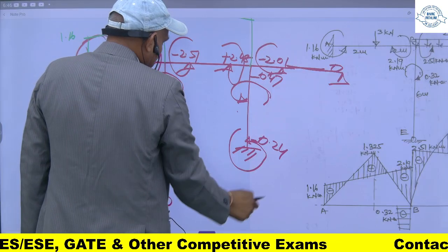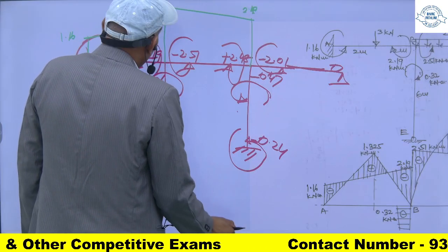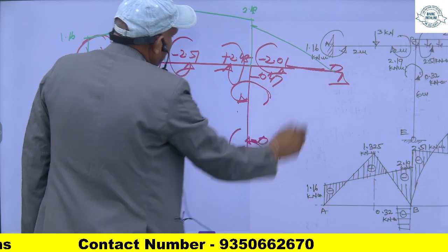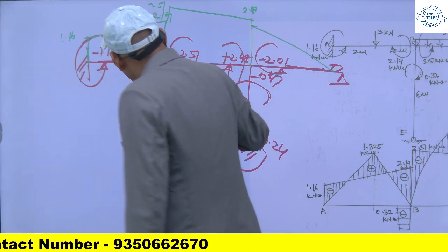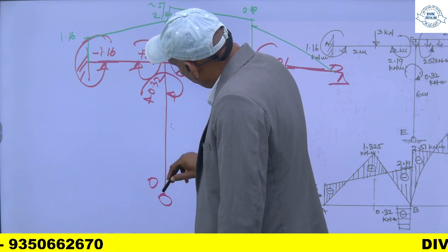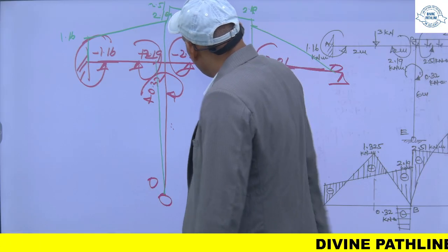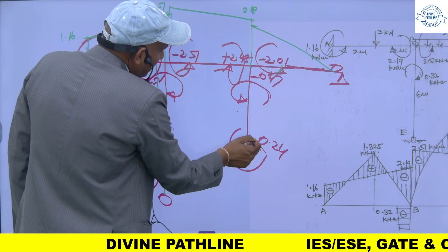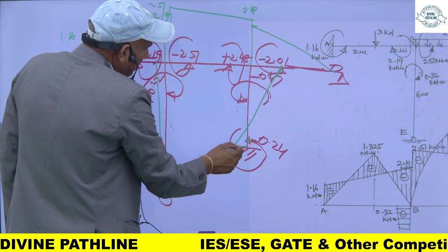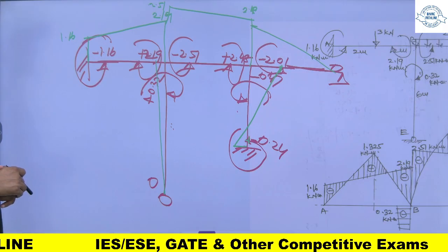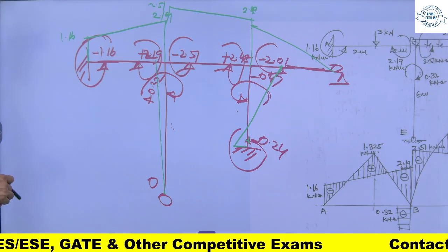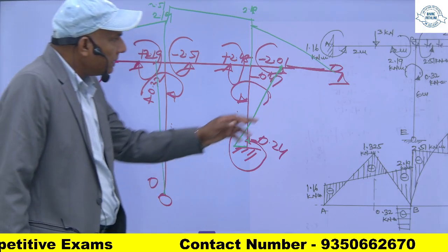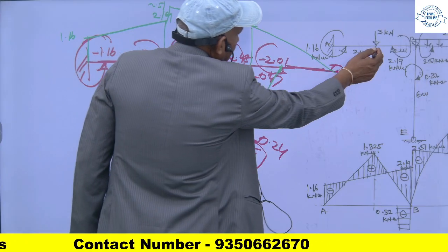This is 2.01 and this is 0. For this, in the direction of the arrow, it will be, and this is 0. It is 0.32. Then this is 0.47 and direction of the arrow is, so it will be like this. And on this, I will superimpose the diagram. Since this load is 3 kilonewton, so bending moment at this will be WL by 4,